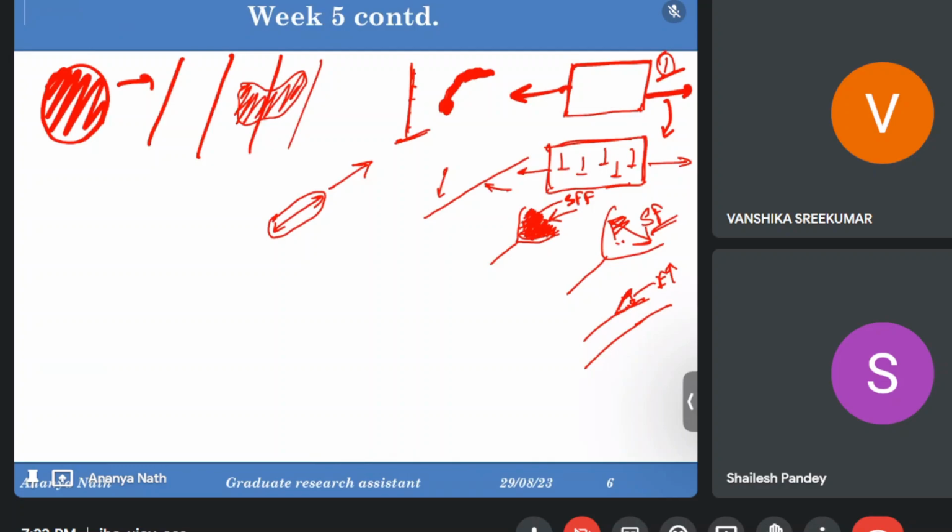Because we know that every system wants to minimize its potential energy. Yes. So the density of screw dislocations will be greater than the density of edge dislocations, as the screw dislocation distorts less. For an edge dislocation, if the energy is higher, it is a normal thing that the edge dislocation will move faster.